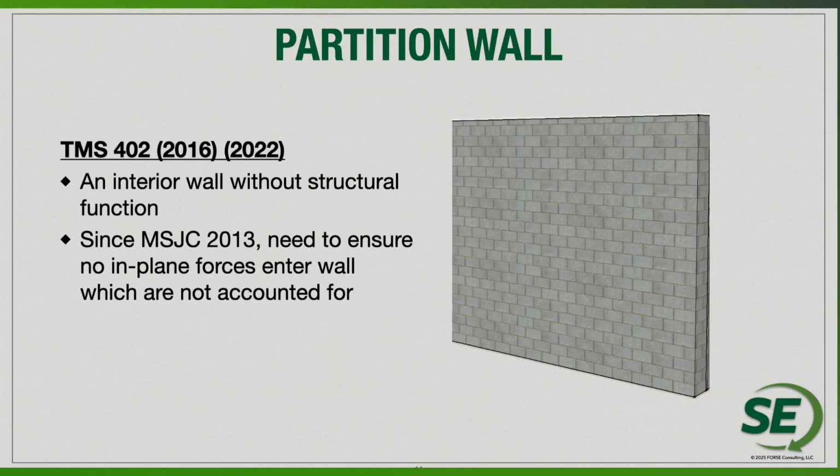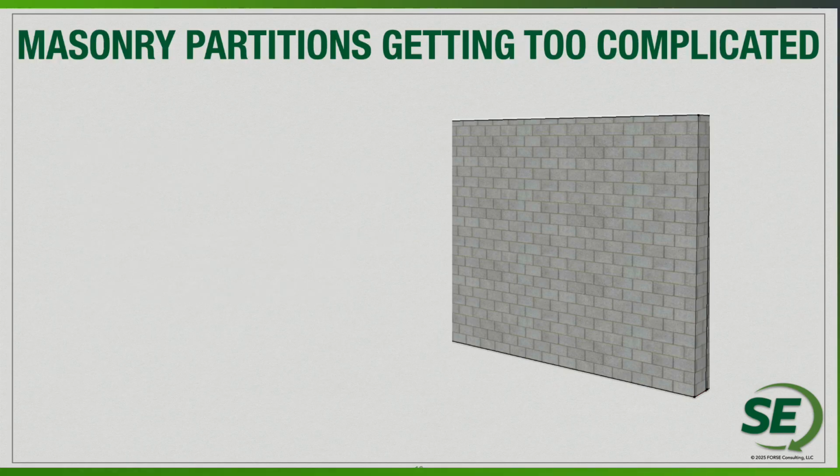We also know that partition walls are not shear walls, so we do talk often in different videos about partition wall design, making sure that we do understand that partition walls are not shear walls and shouldn't be detailed that way. They should be much lighter and simpler elements.